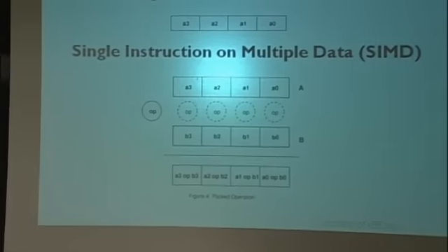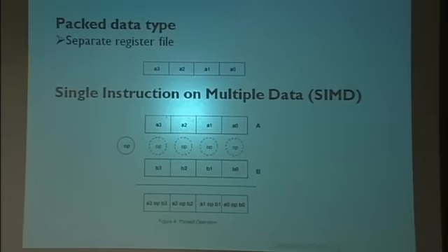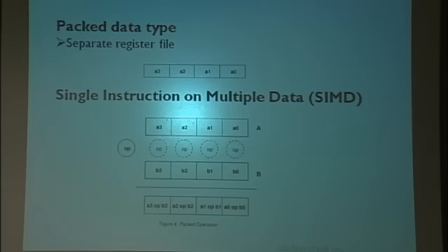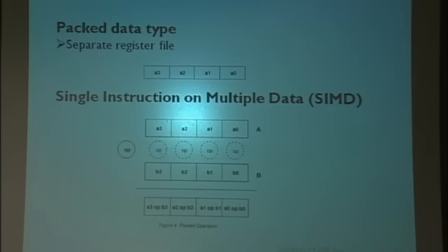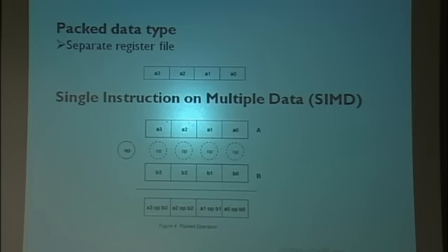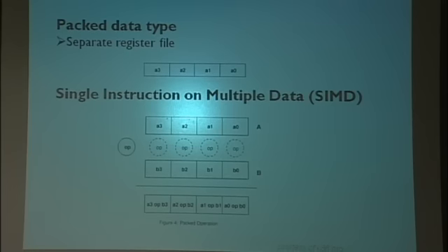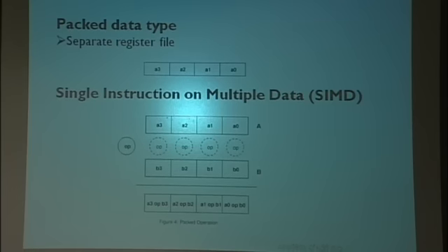And then what you can do is, in a single instruction, instead of doing one large add, with the same type of adder, you can add 4 separate things, 4 small parts. So you're issuing add, but instead of adding 128-bit data, what you're doing is adding 4 32-bit data. The entire architecture looks very identical to adding 128-bit data.